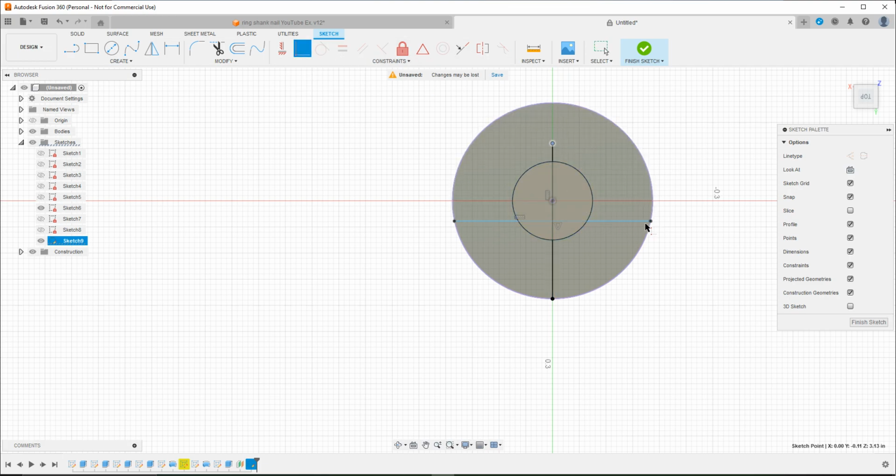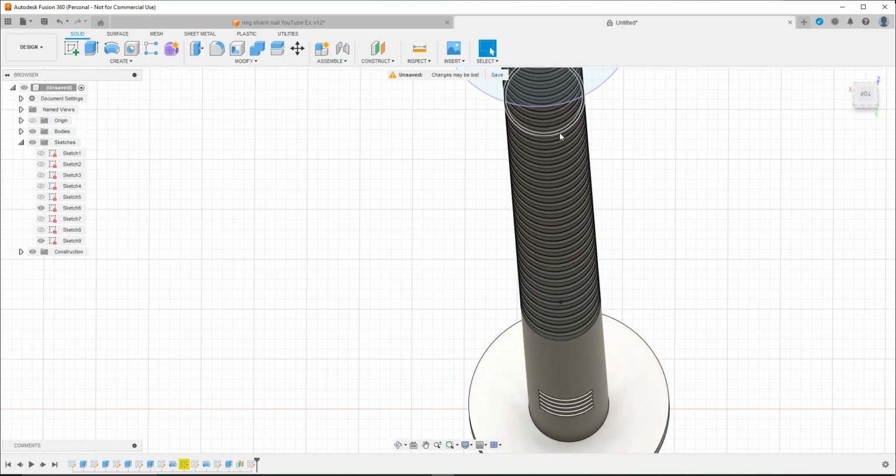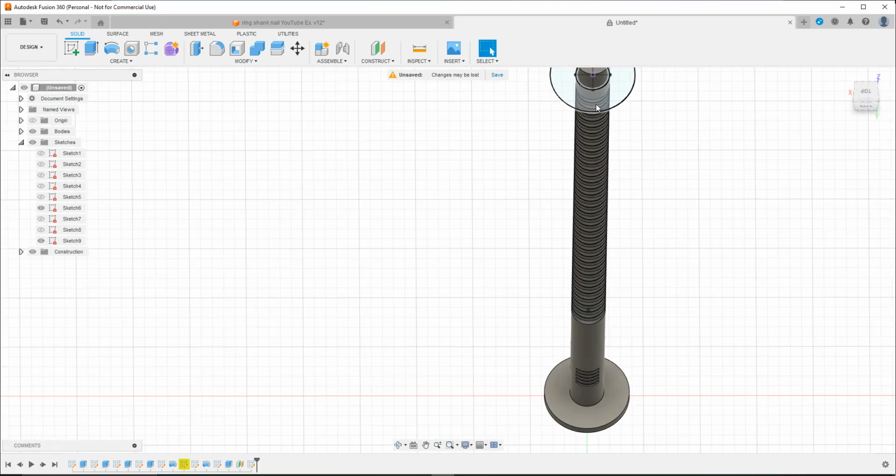I wonder if we can override the old coincidences. No, we're gonna have to delete them. Okay, so right click each one and click delete coincident. Then redo the coincident and click that and this circle right here. And now we should be good to finish the sketch. Now we have 4 points on the exterior.